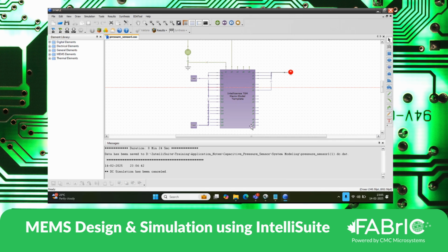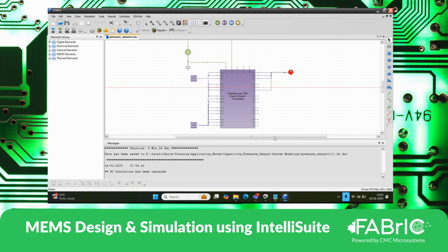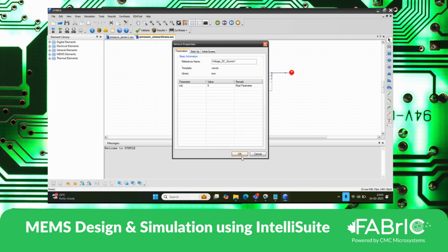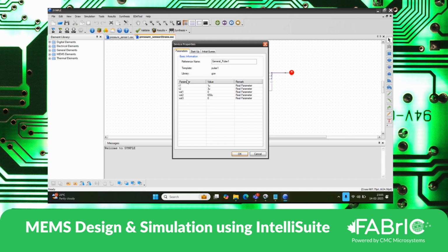Further, we can connect this to other EDA tools as well, and the other circuit part of it also. We can replace the DC signal, which is the bias signal, and we can add a general pulse of duration of 1 microsecond.